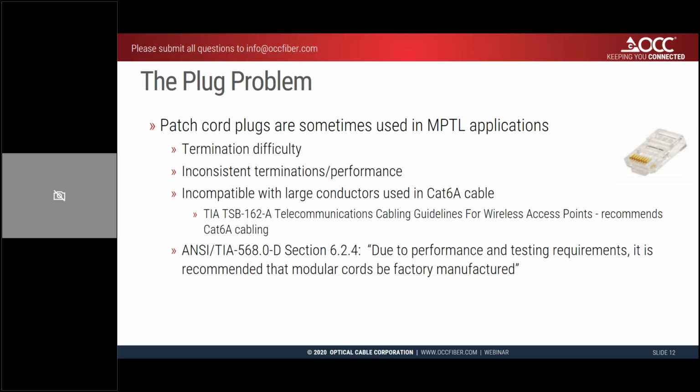And just as a little sidebar here, in 568.0, it does say that due to performance and testing requirements, it is recommended that modular cords be factory manufactured. And that's because factories typically have people who are skilled in the art, and they have the test equipment to properly test these cords and make sure that those plugs are put on correctly.